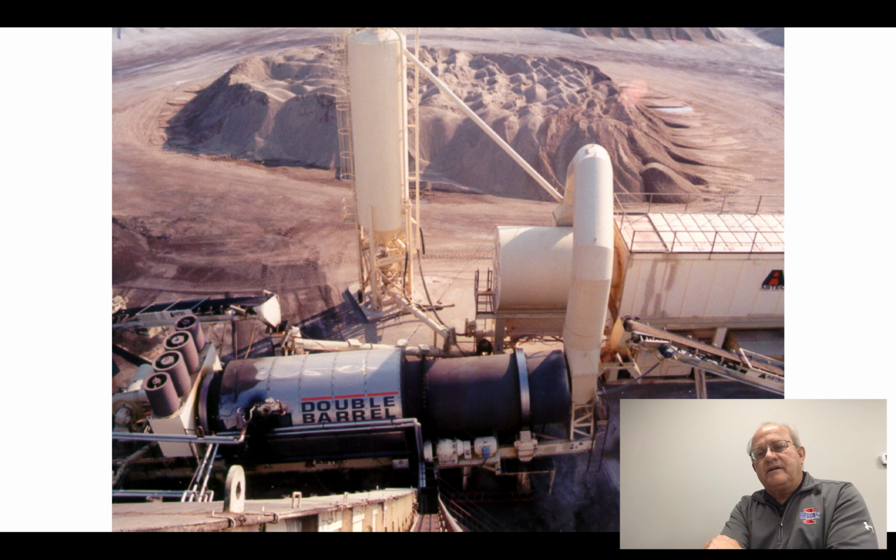Take these aggregates with the internal moisture they have in them, you run them into the plant. The heat from the burner heats these up to the 350 degrees range to create the mix by taking all the internal moisture out of the aggregate. Kind of a quick number just to make you understand how this process works. A general rule is for 1 ton of aggregate, it takes 300,000 BTUs to raise 1 ton of aggregate from ambient temperature up to the 300 degrees.